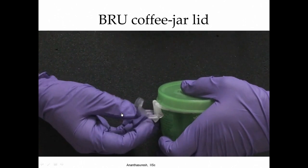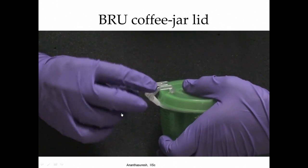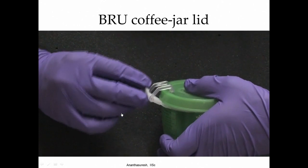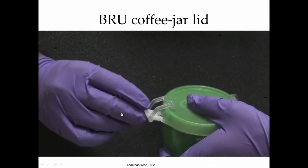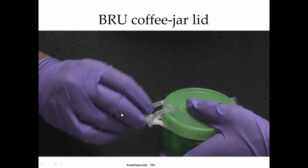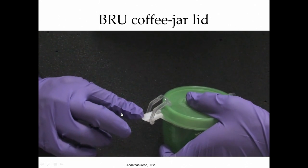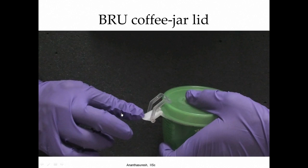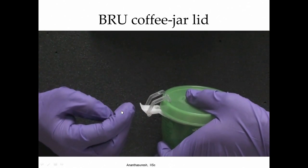So, right now what you see is basically like a serial chain, there are two rotations there. The moment you place it on top of that, that becomes a slider crank linkage, and then once you bring it far enough and it touches the lip on the can, it becomes a structure, cannot move, but you can still push it. At that point the transparent body will elastically deform and get this motion.